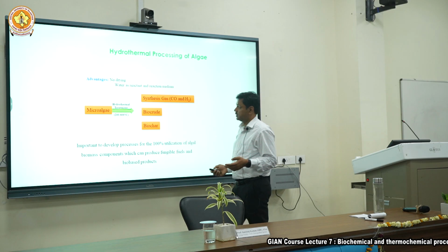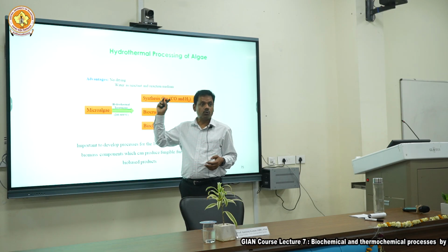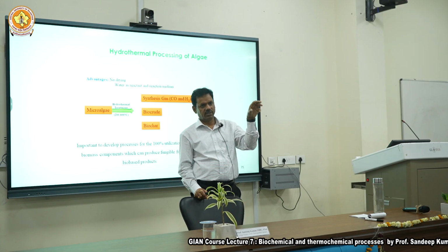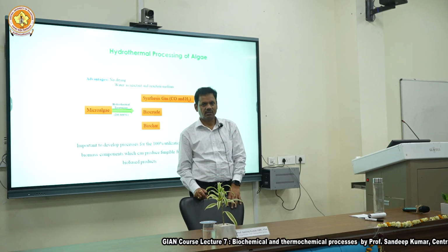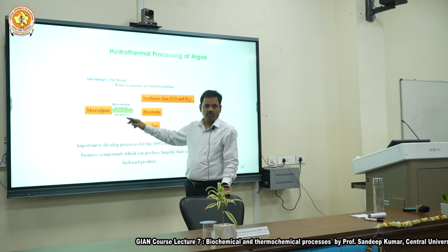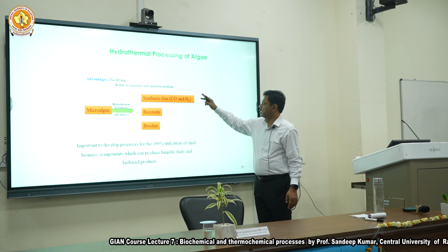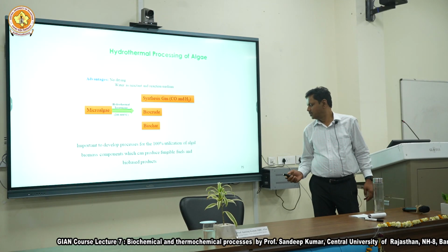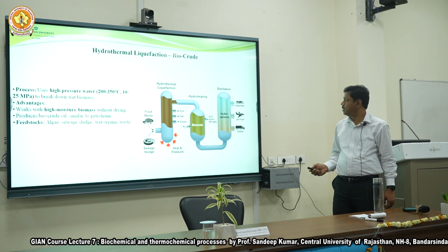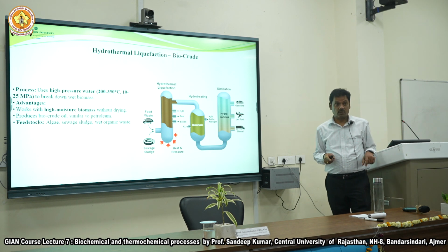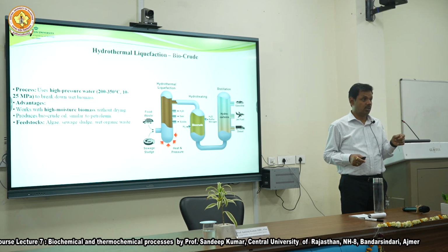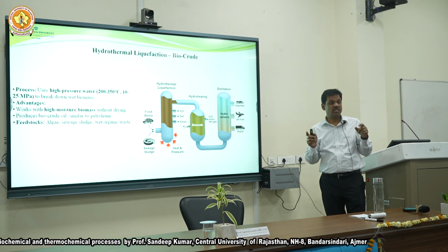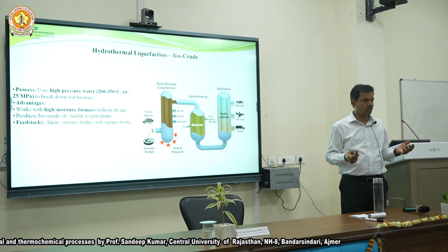Then once you concentrate it to 8 to 10%, you can do the hydrothermal process, and I showed you the graph, different temperature, different solvent properties, and you can play with those numbers between 200 to 600. You can make whatever you want with all these things. So HTL has picked up a lot recently. You are following that hydrothermal liquefaction process is becoming more popular, especially for algae, sewage sludge, food waste, where there is a lot of water.